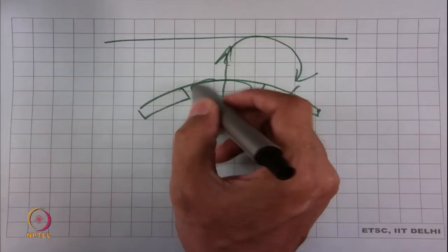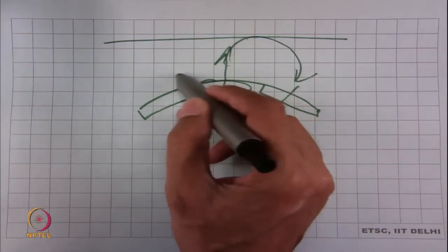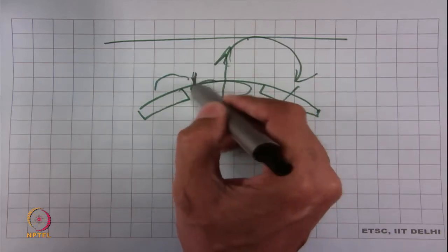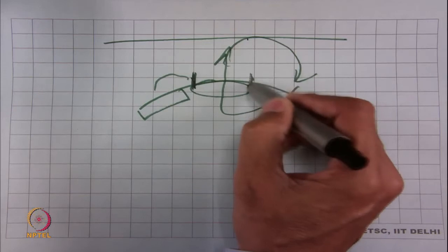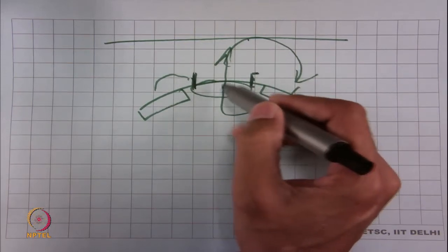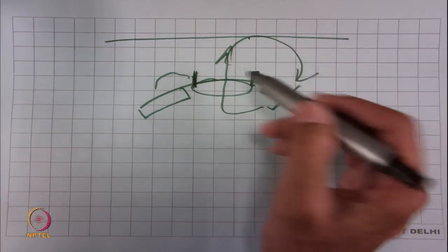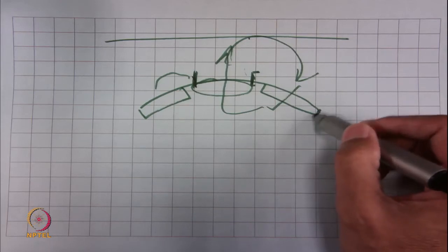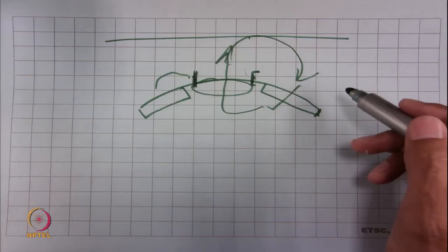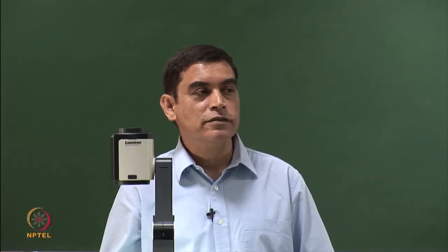We also, while doing all this, discovered that irrespective of this cover or not, there is also a certain amount of air that just comes back in because of the natural flow of air. So we did some redesigning to provide a small duct of about 20 millimeters just ahead of the propeller fan that would direct the flow vertically upwards. And then we had to go through the usual tests, re-optimization, and some of the tools available when you have space constraints are to increase the fin density, to play with circuiting, to optimize the circuiting better, and all those were done.